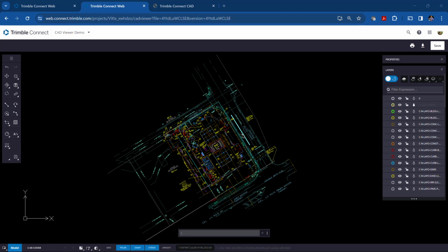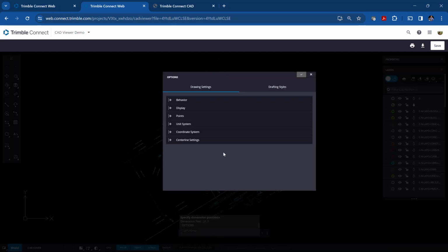So understanding the options or settings for your drawing is going to be important, especially when you look at your text styles and your dimensions if you start dimensioning some of these objects. So to get to the options on the command line, if you type in options, you'll get to this options dialog box. Now there's a couple other ways you can get to it. You can go to text styles or dimension styles and you'll get to the same location.